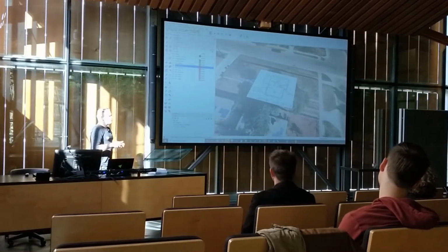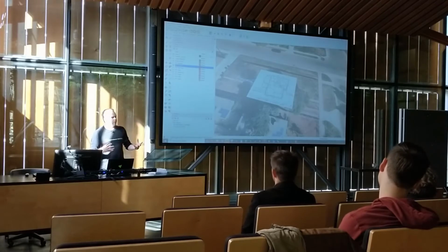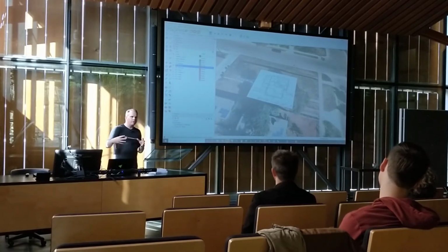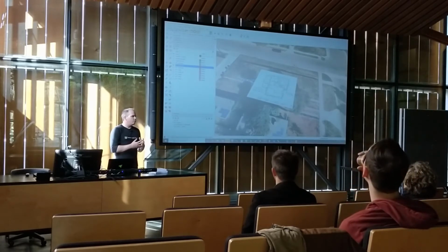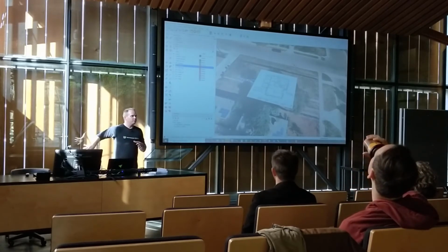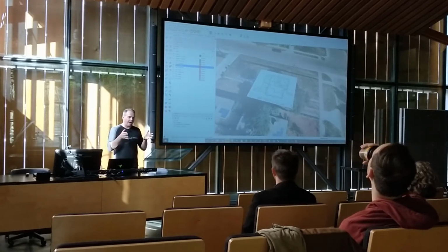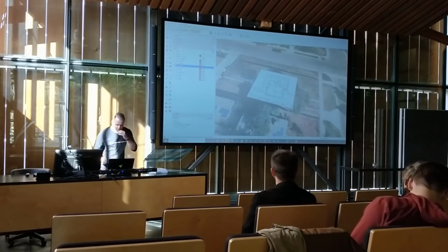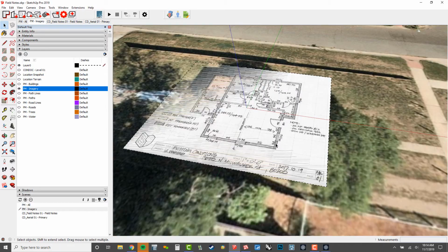Now, as I mentioned, this is all loose scale, and maybe when you do this, your field notes aren't going to be as precise, and they're not going to line up perfectly. It doesn't matter, because we're now going to rebuild this model and type in precise dimensions, and then we're eventually going to abandon the field notes, because at some point we say we have our existing conditions model, we're good to go. So let me show you that. If I just zoom in here, this is how I would start.